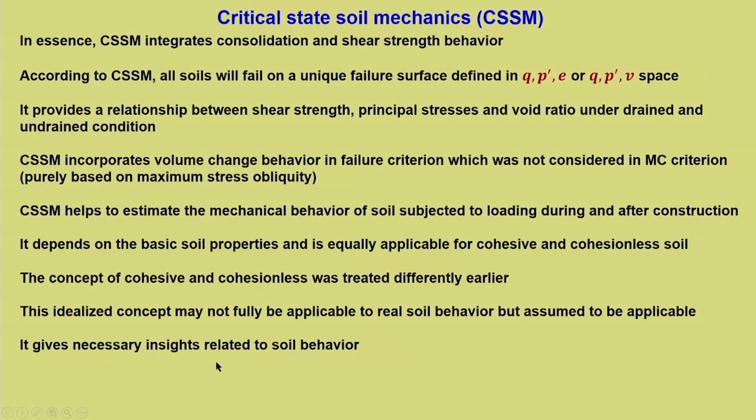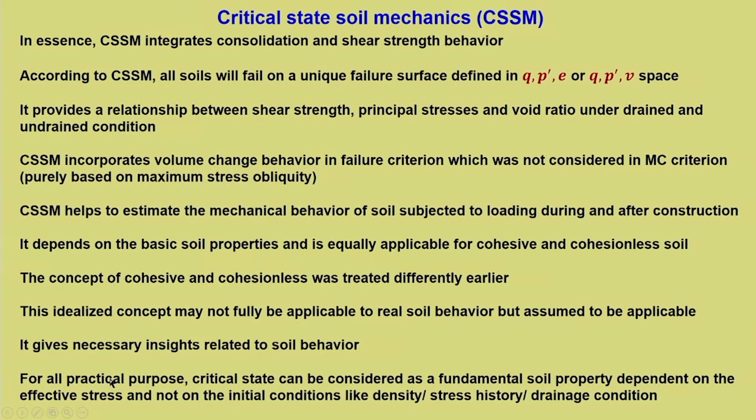It gives necessary insights related to soil behavior. That is what is more important for an engineer planning any sort of analysis or design. Certain insights related to soil behavior are important, and for that we need a framework, and that framework is offered by CSSM. For all practical purposes, critical state can be considered a fundamental soil property dependent on the effective stress and not on the initial conditions like density, stress history, or drainage condition.